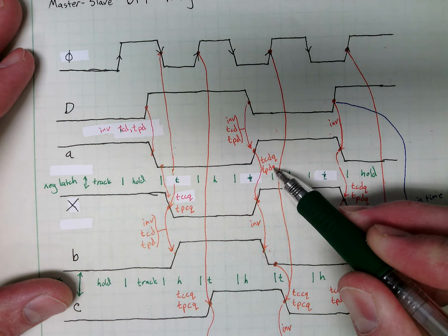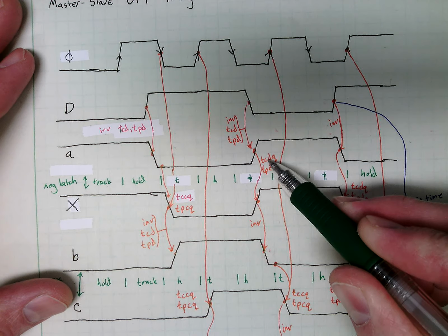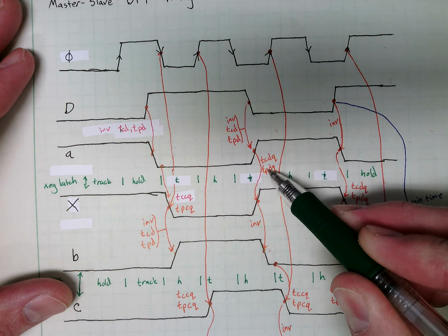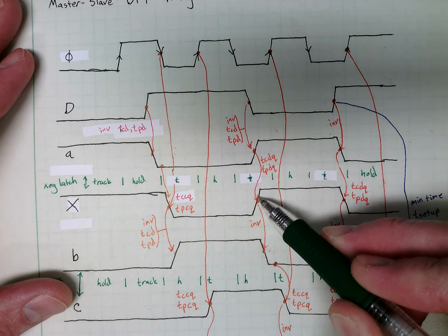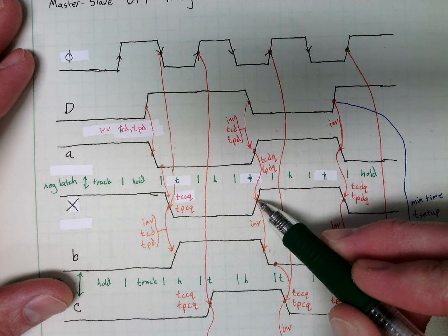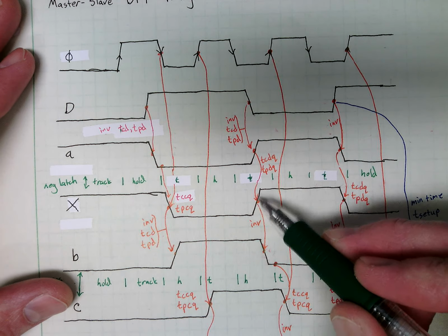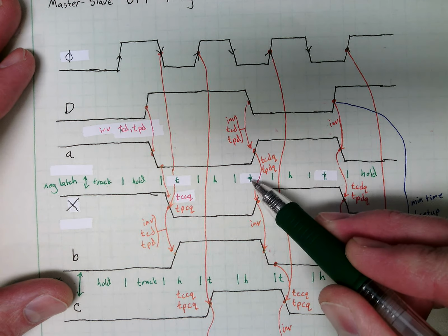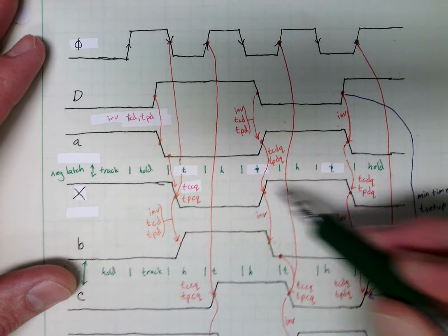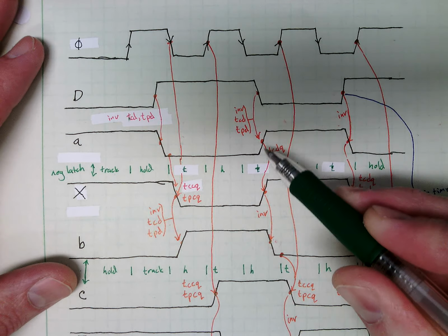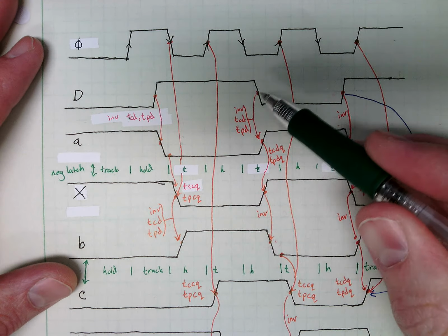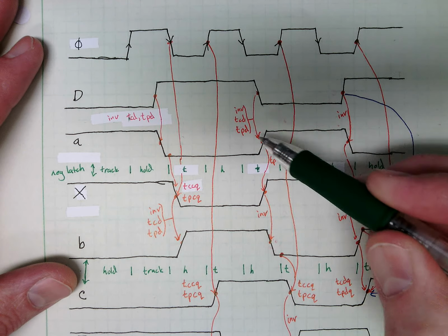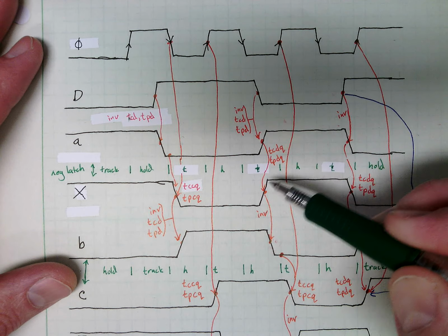D to Q delay: contamination is the minimum, propagation is the max. So this is D to Q delay for a latch. They always go the same direction because it tracks. And then there's an inverter here. We have an inverter here. So we have a chain of events. We have an inverter delay, we have a D to Q delay, and then we have another inverter delay to